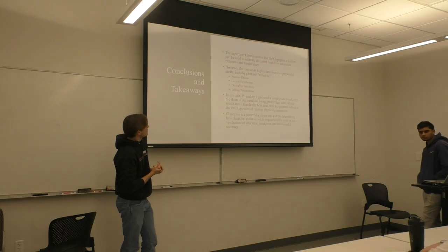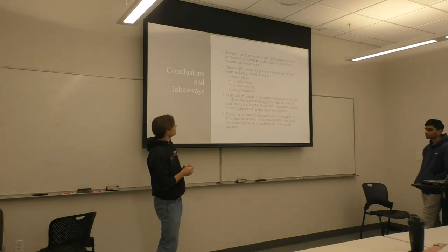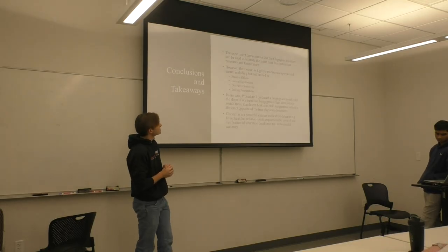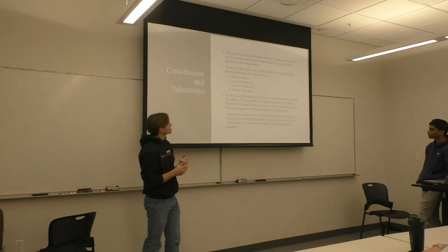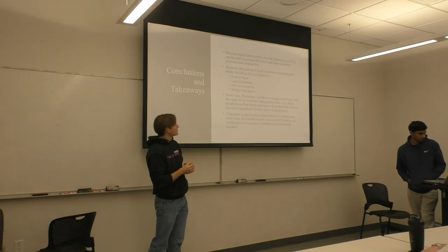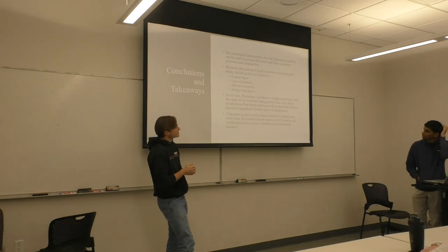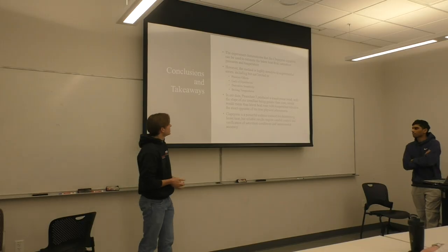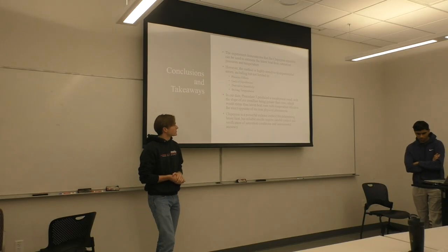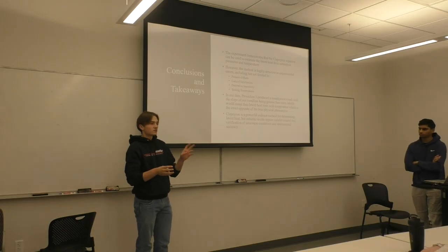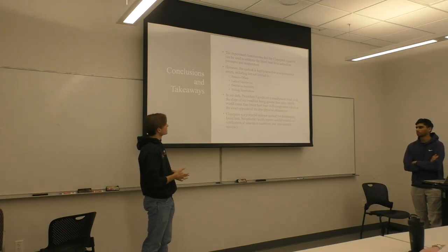Overall, the experiment demonstrates that the Clapeyron equation can be used to estimate the latent enthalpy from saturation pressures and temperatures. However, the method is highly sensitive to experimental errors, just like any experiment, including but not limited to pressure offsets, lack of equilibrium, derivative sensitivity. That's kind of why those first two procedures didn't actually look very good.